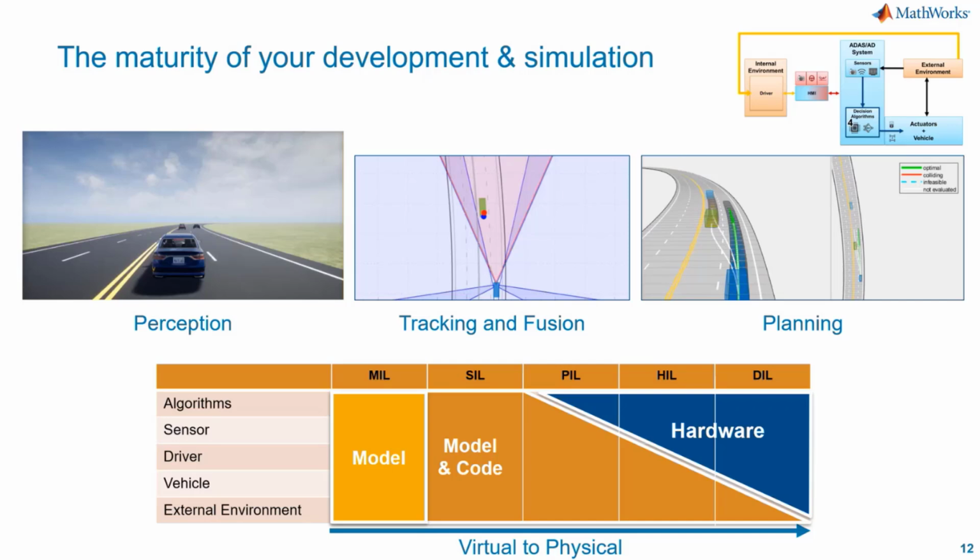So there are different levels for performing the simulations. We usually start from model in the loop testing, where the models, let's say the models for the algorithms, or for sensors, driver models, vehicle dynamics, all the scenarios and scenes, are regarded as models, right? So model in the loop means that we close the loop and perform simulations in our desktop simulation environment, right?